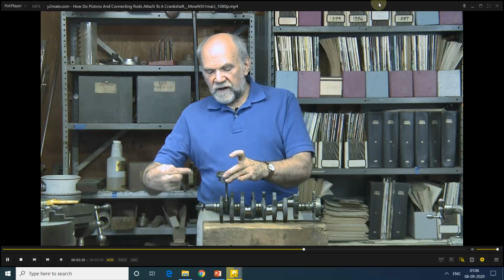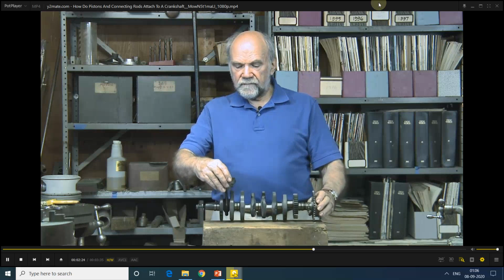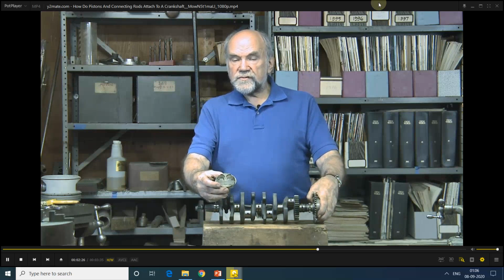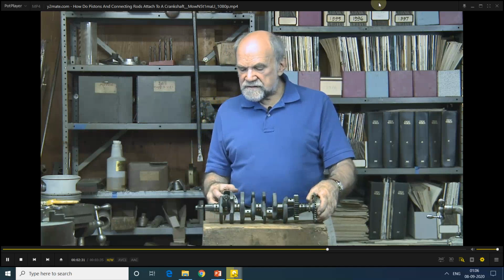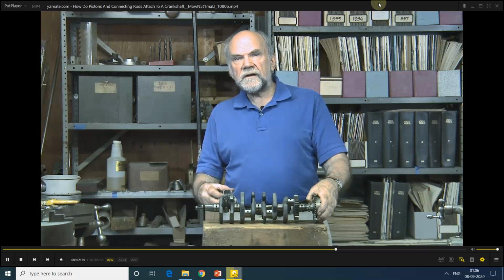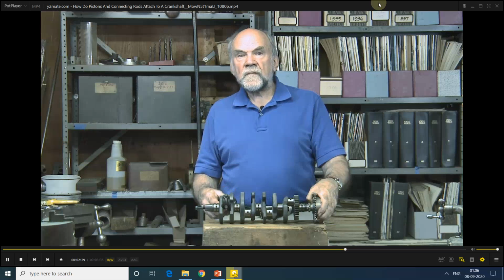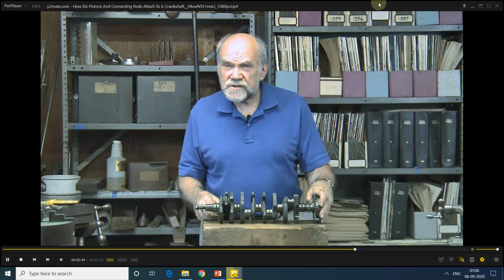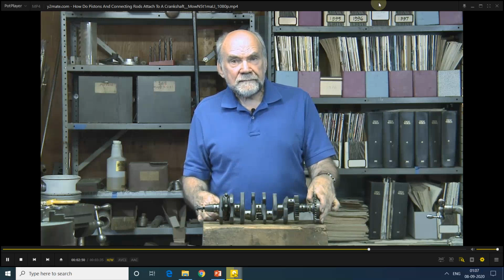when the crankshaft revolves, the piston rises and falls. So the straight line motion of the piston up and down in the cylinder bore is, by means of the wrist pin, the hinge point, and the connecting rod, transformed into rotary motion at the crankshaft. Now, to anyone who's ever worked with gas turbines or jet engines, this just seems hopelessly medieval. The idea of pumping air with pistons.